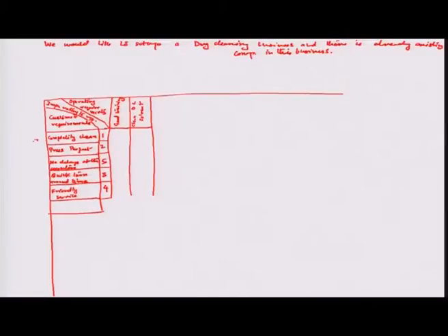We can also check the filters related to the dry cleaning machine. So we should have clean dry cleaning filters. If the filters are not clean from time to time, then there is a reason why dust could be carried back into the clothes while the cleaning process is on, and it might result in some kind of unclean surface or dusty clothes being given. So that's another aspect related to the operating requirements.